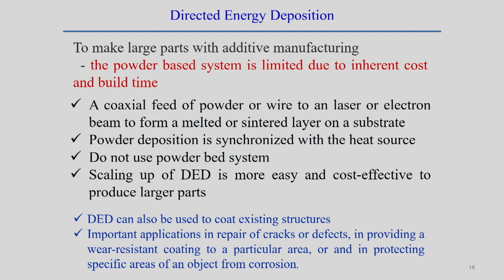Of course, we do not use a powder bed in this process, and scaling of DED, directed energy deposition, is possible in an easier and more cost effective way. When you try to produce a very large, big product, directed energy deposition is more suitable.